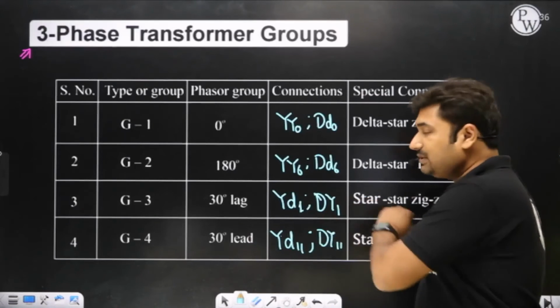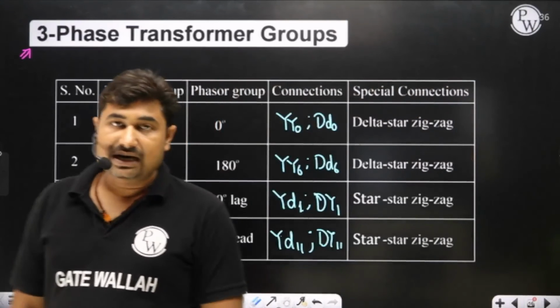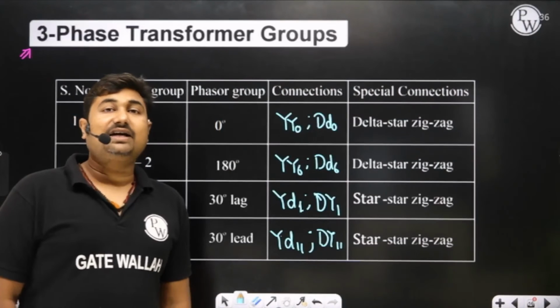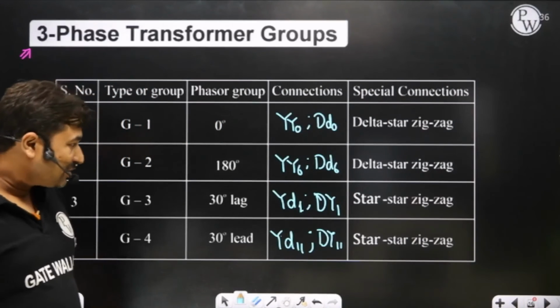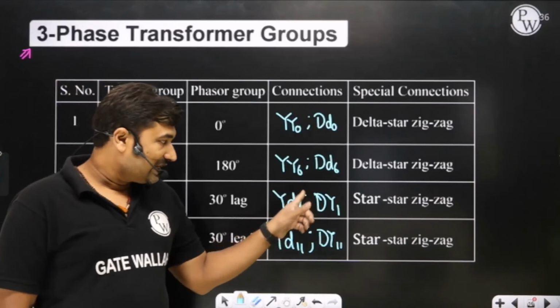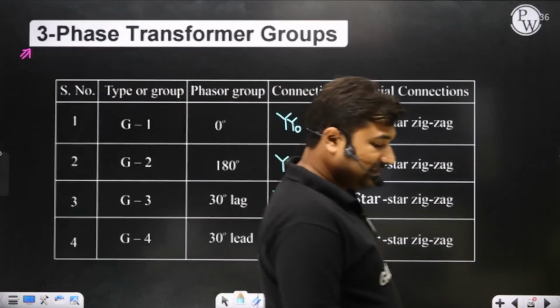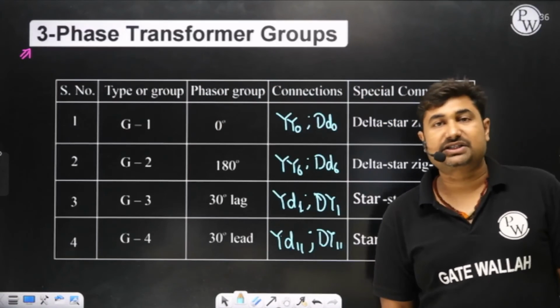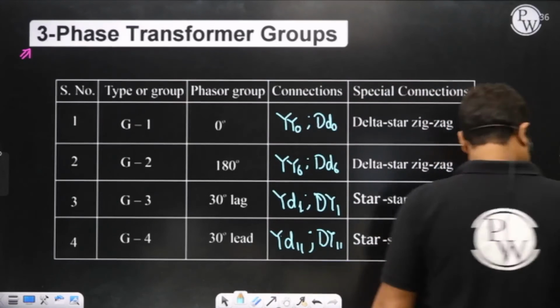Once we know about the insulation level desired for delta and the insulation level desired for star, as well as other requirements like harmonics. So after the harmonic concept, you came to the information that delta star 1 and delta star 11 are the preferable connections for a distribution transformer. Star delta is not preferred.